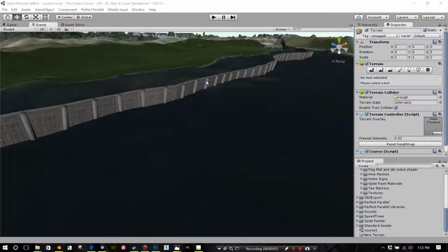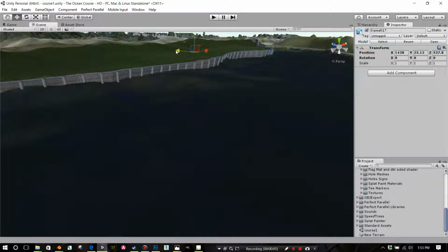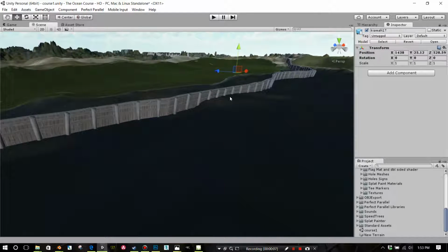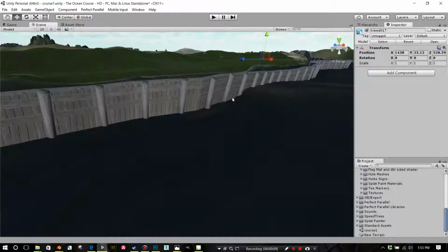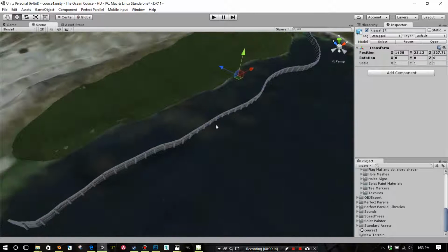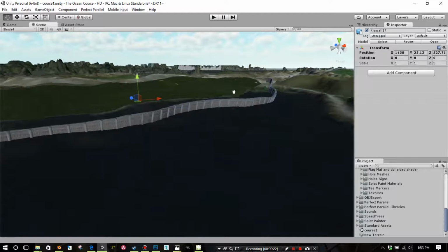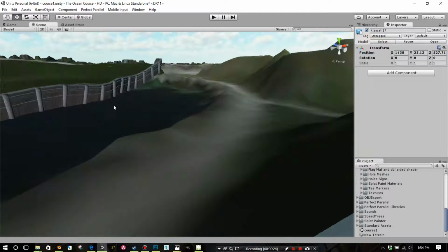Okay, you guys, this is kind of one of the neater tutorials. I really like this process. I'm creating a bulkhead by not hand placing it, but instead using Blender to create it for me. What it's doing is following my outer mesh, my CourseForge mesh, and it's following the undulation of that as well. You'll see that it actually even curves up here.